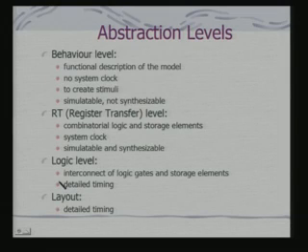Gates will have different timing depending on the technology that is being used for implementation of the gates. So, when we come to the logic level, we provide the specification in terms of actual logic gates and the corresponding storage elements. So, the detailed timing can only come at a logic level. And the layout level tells you physically how these transistors are put onto silicon, what is their interconnect pattern, and that will provide you the absolute detailed timing.